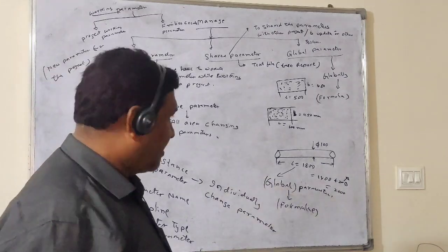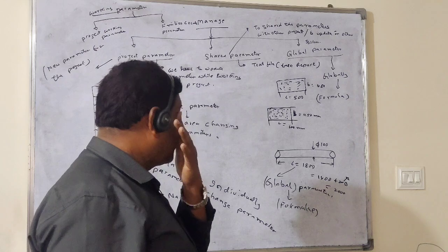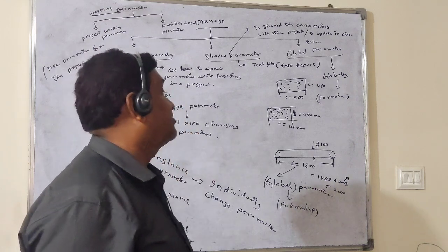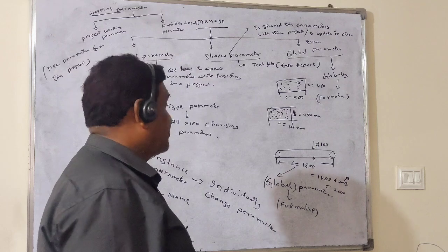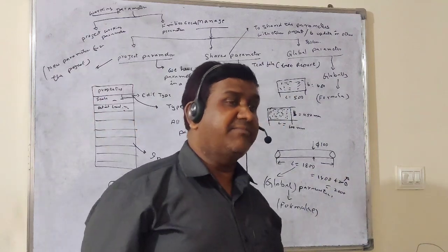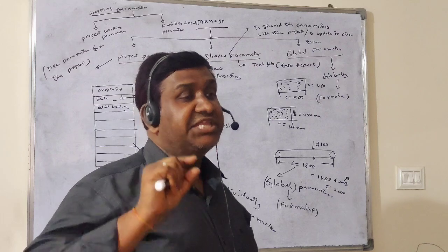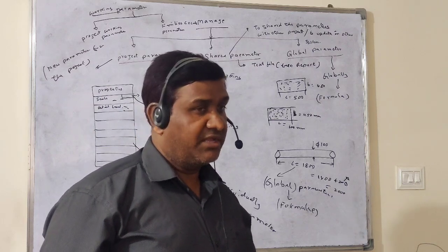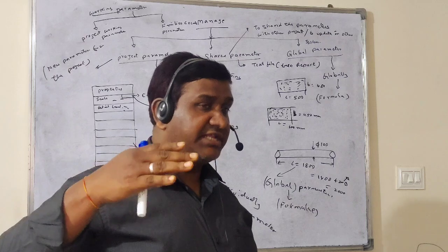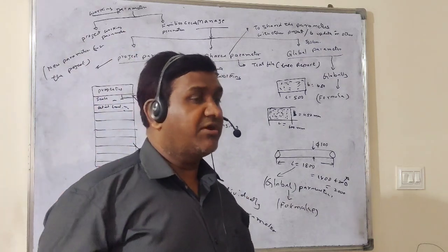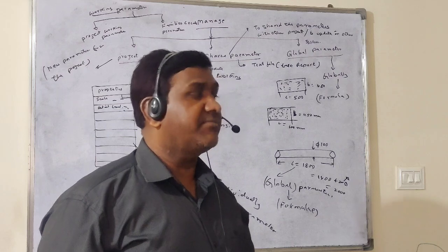Okay, so I think you somewhat got an idea about that. Just remember it, and while doing the practical you may get more clarification on it. Just remember verbally: instance parameters are individual changing information of each and every component. But if you want to change entities in bulk, meaning many entities at a time, then you have to go with type parameters.